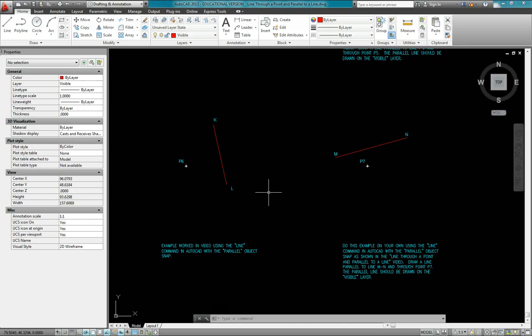And there's a couple reasons you'd want a one-time override. If you have a lot of your running object snaps turned on and you have a really tight drawing, in other words, a lot of entities in the same place, sometimes you may find it difficult to get AutoCAD to snap where you want it to snap.